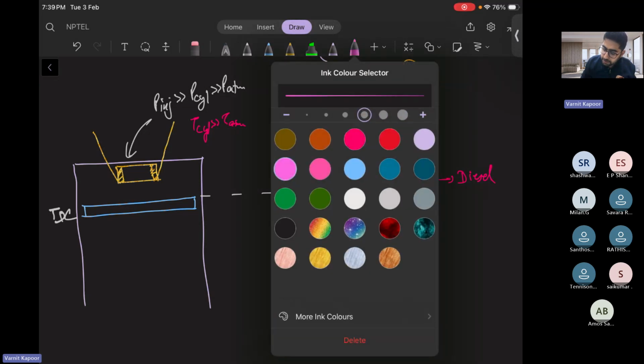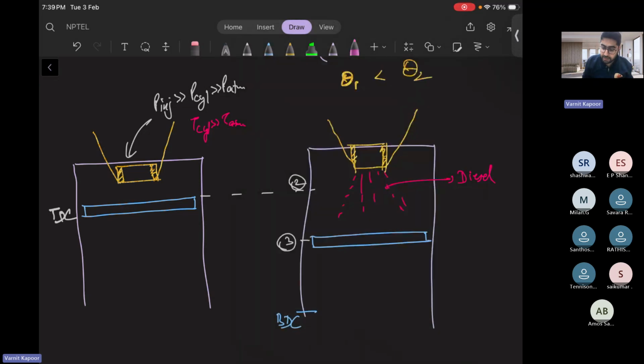And eventually, if I'm injecting fuel, there will be some cutoff also, like from which position to which position my fuel is getting injected. And when the fuel is getting injected, the temperature will rise higher than the self-ignition temperature, not at point 2, but at point 3.